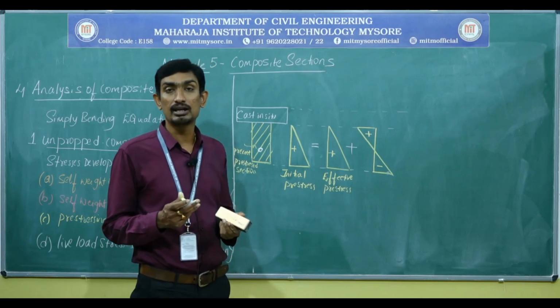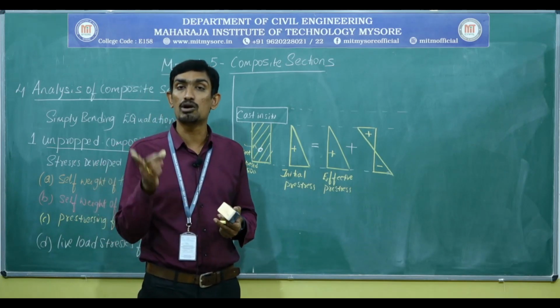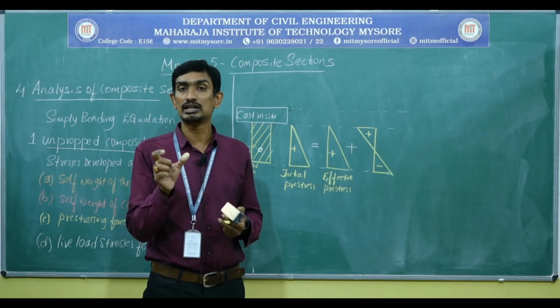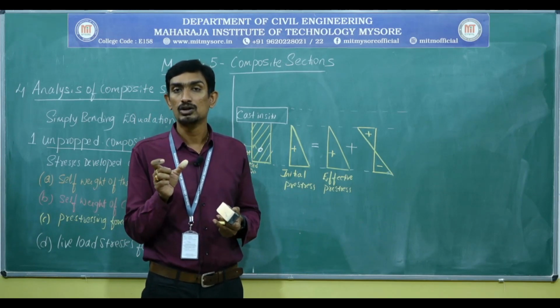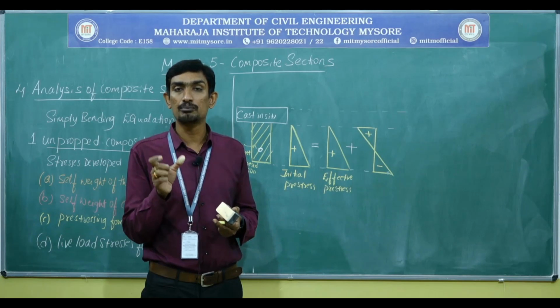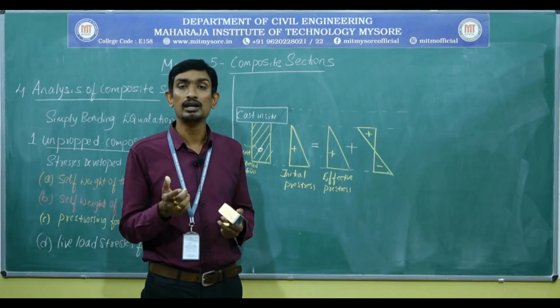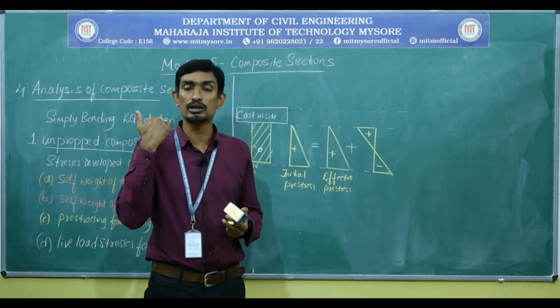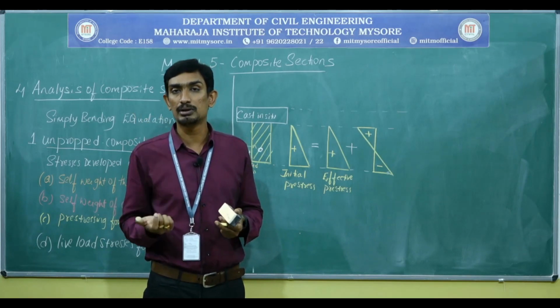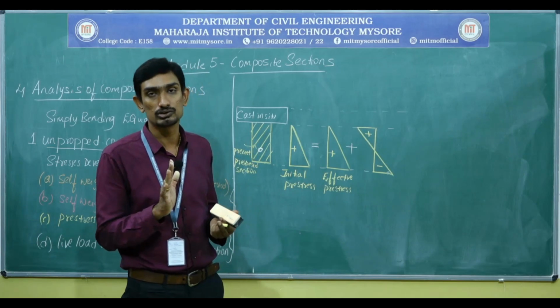I think this particular case has been explained in module number 1 also. When the section is subjected to bending, that is due to dead load, then automatically the compressive stresses will be developed at the top and tensile stresses will be developed at the bottom. Same thing holds good here also.